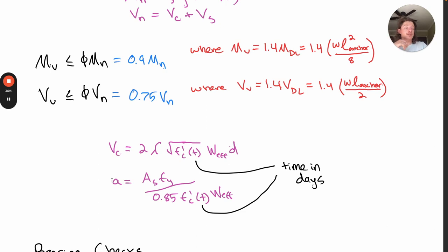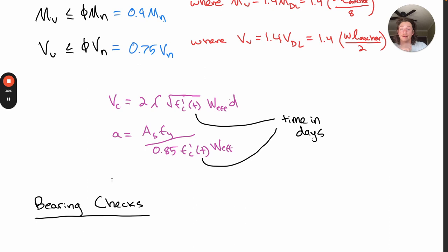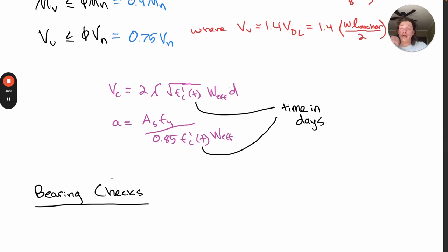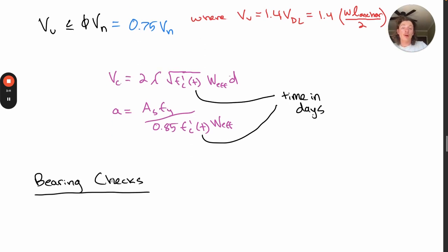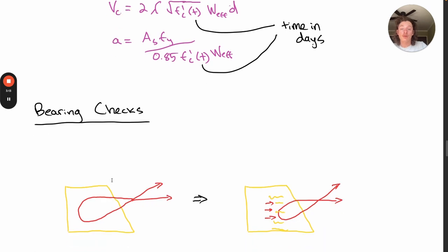The final condition we also want to check again is bearing. The beam may have sufficient strength as a whole, but we also want to confirm that the cable point loads won't overcome the bearing strength of the concrete at that time and pull out of the anchor and cause damage. Once again, the loads are going to be less than they are during the full loading when we did this check in the previous analyses, but the strength of the concrete is also going to be less. So we want to redo this entire check to make sure that it is all sufficient.